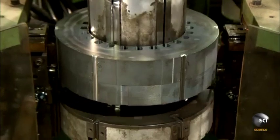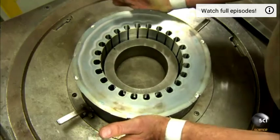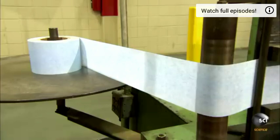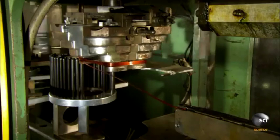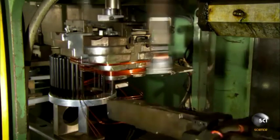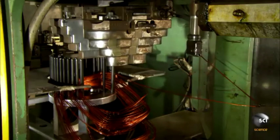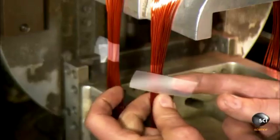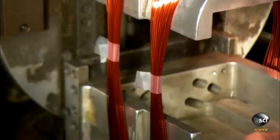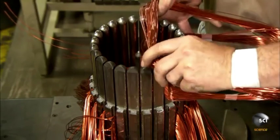Machinery lifts the stator core out of the assembly device and transfers it to the next station. Here, an automated system insulates the numerous slots in the core. Meanwhile, at another station, an automated system winds copper wire onto a mandrel. This configures the copper windings to fit the core slots. Once all the windings have been correctly arranged on the threading tool, the technician is ready to transfer them to the stator core.